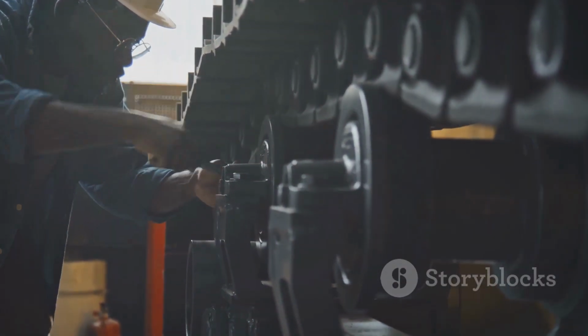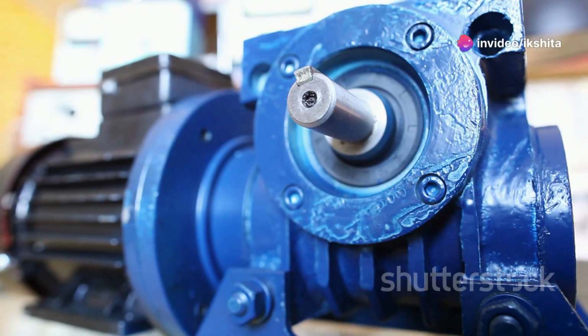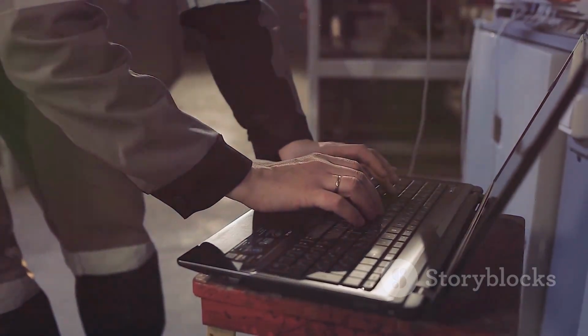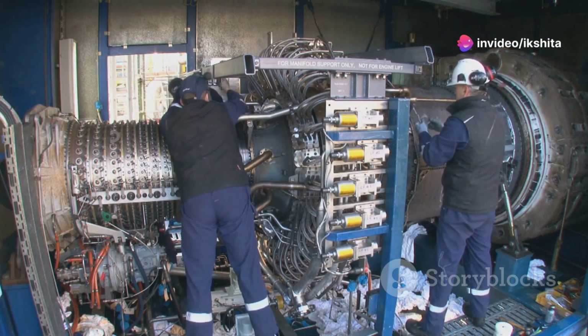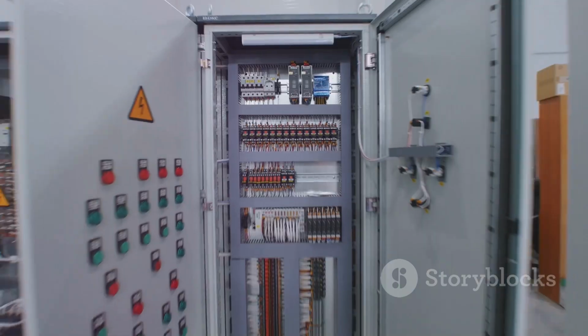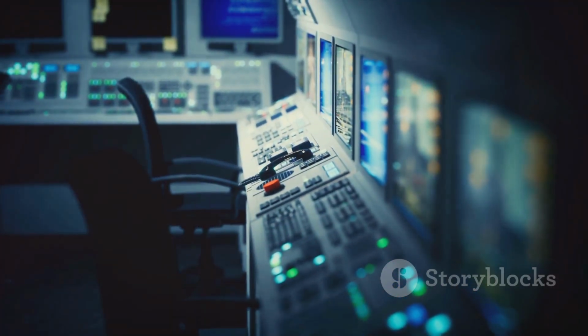Unity power factor is ideal, creating a balanced operating point. Armature reaction affects voltage regulation in generators and torque production in motors. Various techniques, like compensating windings and field excitation control, help mitigate its negative effects. Understanding armature reaction helps us design, operate, and maintain synchronous machines for optimal performance. These machines play a vital role in our electrified world, quietly and reliably powering our lives.